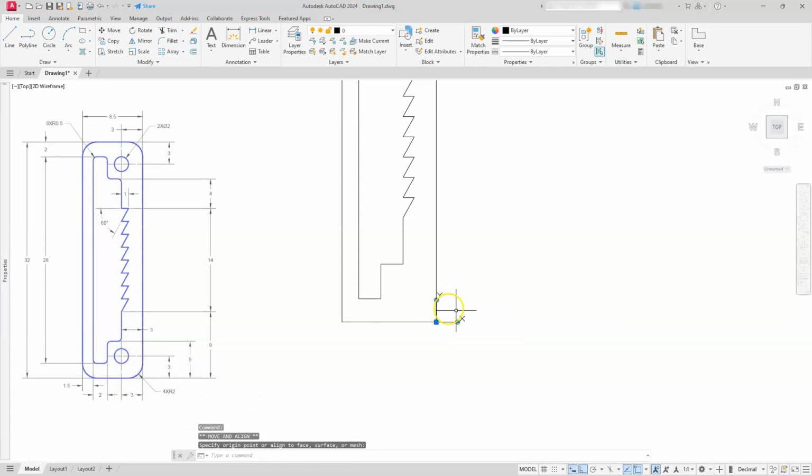Now, if you're looking at the drawing, it says that the location of that circle is going to be 3 going this way and 3 up. So I'll go to circle, center diameter. I'm going to type in its coordinates. It's going to be -3, 3.